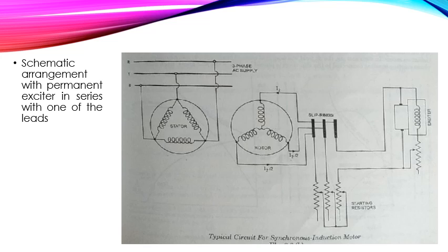However, the extra cost, low efficiency as compared to that of the standard types, the small copper space available with a distributed rotor winding, and the necessary compromise between the excessive ring voltage at start or excessive rotor current in operation are severe handicaps, right?